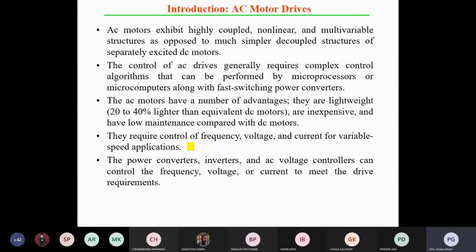As per the changing of your motor load, the motor actual speed will also vary. So you have to keep that motor actual speed fixed. You can sense the actual speed and process it through the processor unit, meaning the controller unit. The controller is situated in the processor unit. Processing that value, you can mitigate that error, and you can find the suitable PWM.